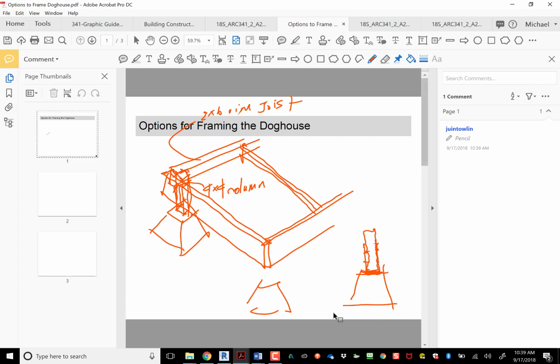But you need to be able to fix this 2x6 to some wood without hitting the metal. It may be that you don't need to extend the 4x4 up. There may be a way where you can hit the side of it. And in that case, you could drop this 2x6 flush with that piece of metal, in which case your doghouse could be shorter, which would be good.